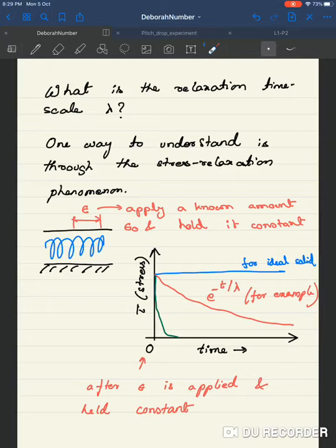For example, egg yolk, that kind of material, looks like a fluid, right? Or even the egg white, rather. Egg white is probably a better example. The egg white looks like a fluid, but it probably has a finite relaxation time scale. So if you are trying to observe a phenomenon that is close to that, then you will have to consider a more elaborate scheme. And the kind of discussion we are going to do for the rest of this class may not be sufficient, right?